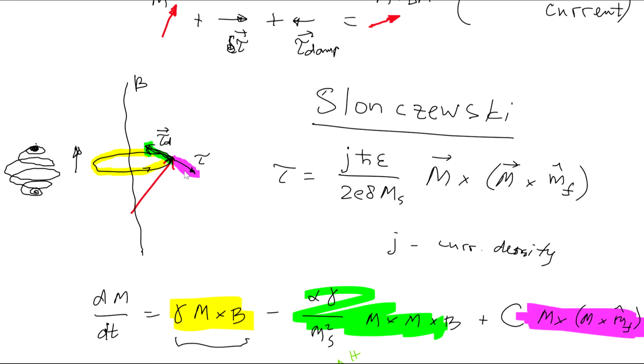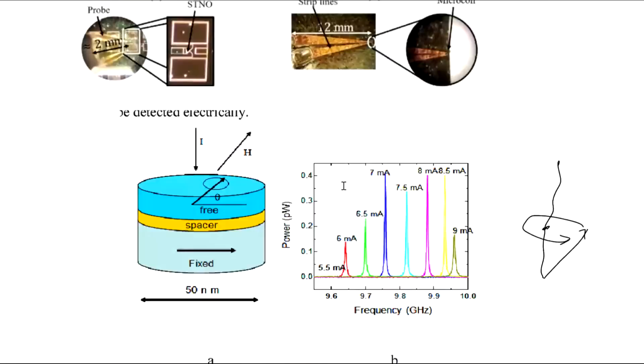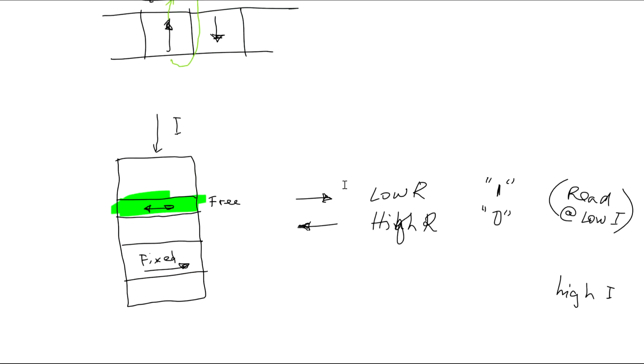It applied huge torque, and it rotated it, and it oscillated to the spin down state. So applying fairly high current pulses can allow you to achieve switching at high currents. And if you drive current one way, you will switch it in one direction.